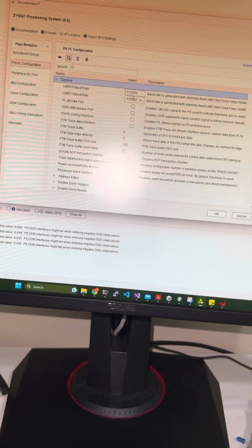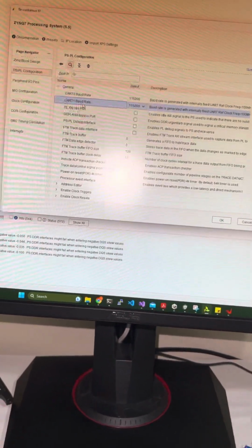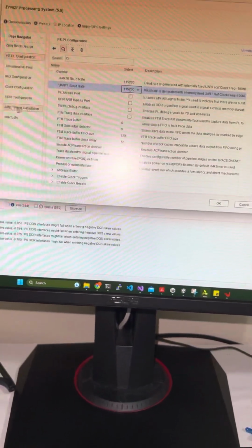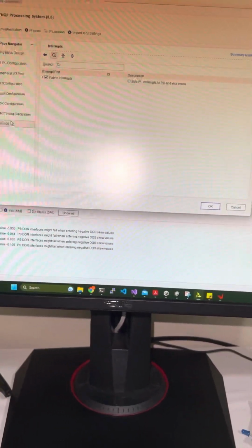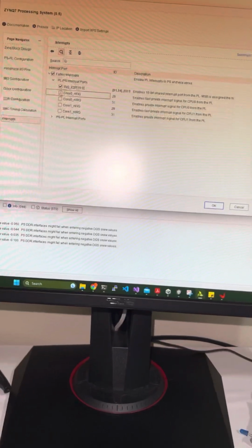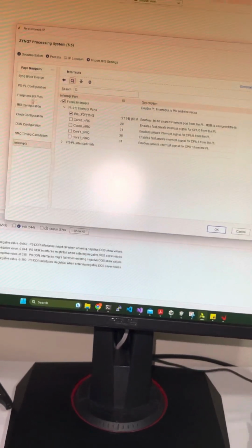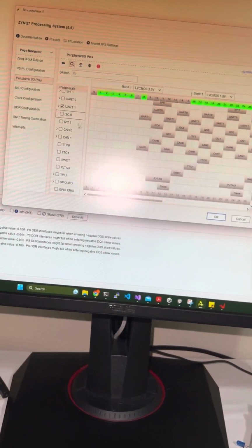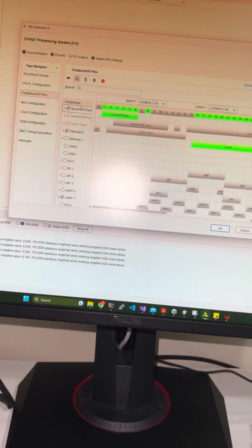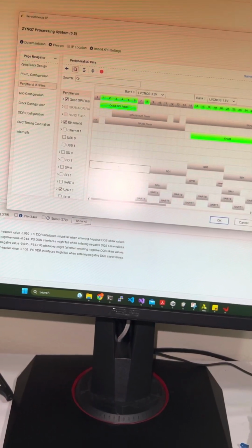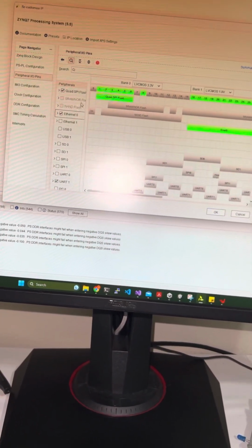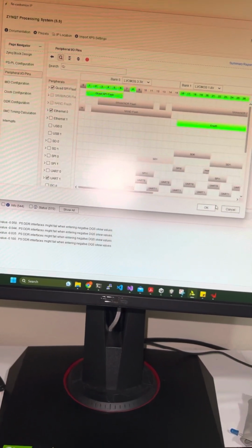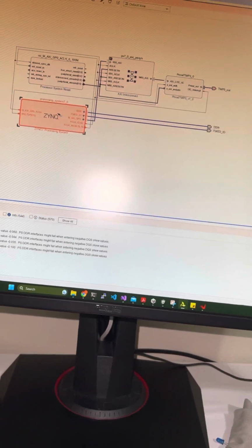And over here you can change the baud rate. So UART1 baud rate, I set it to 115.2. I still have the fabric interrupts up here. And then for the peripheral IOs, here's the UART1 that's turned on. Everything else is turned off, except I left the Ethernet and quad SPI, but it was fine for this run.